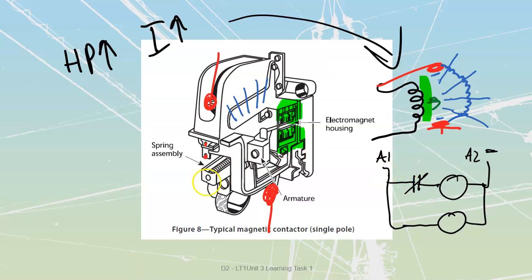What we have, though, is that when we pull this in, it gets operated once it gets pushed all the way in. So when I provide power to my coils, both of my coils are going to energize. Boom, the armature drives in. As the armature drives in, it is then going to open up that coil over there, and then we are only going to be maintaining current through the smaller coil, which is going to keep us held in, or sealed in.